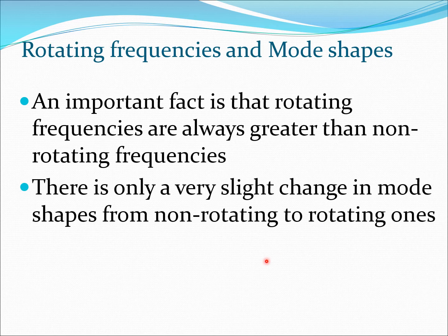An important part which comes out of all this study is that rotating frequencies are always greater than non-rotating frequencies because you have the centrifugal stiffening, but there is only a very small change in the mode shapes from non-rotating to rotating, and that is why you can frequently use the beam functions in the rotating beam problems.